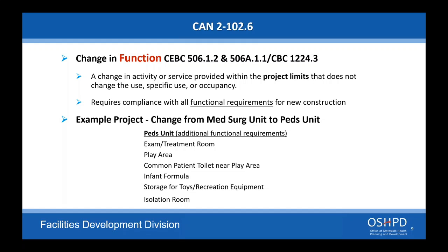What we're stating is that if you're remodeling, changing the use of a space, there are going to be requirements for fire upgrades. Fire life safety is big, and we're not going to provide a non-safe condition. The question is kind of all over the place, so I'm trying to focus in on where you're going with this. But if you're doing a change in use, the corridor may need to be upgraded depending on what that use is changing to. You can't have a non-compliant corridor system for the type of use it's going into.